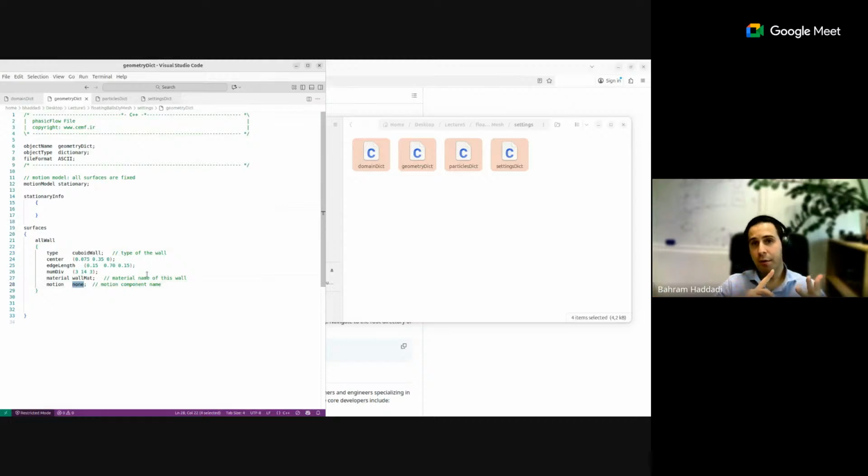And there is also a third one, which is the most relevant for CFD-DEM or for PhasicFlow Plus. Basically, you can import the geometry from the CFD side to the DEM. We have some examples. If you check through other examples, you will see that you can import the boundaries of a CFD simulation as the walls or as the surfaces to the DEM side. And that gives you a very nice transition between CFD and DEM on the geometry side.